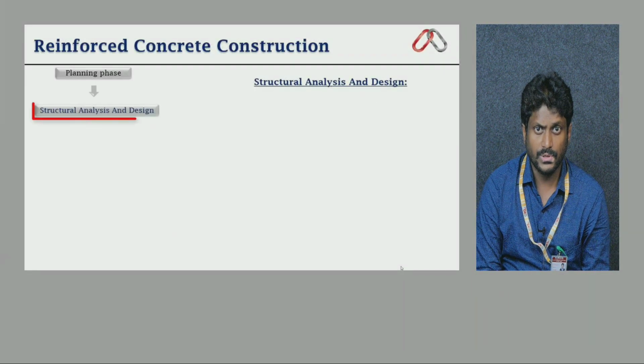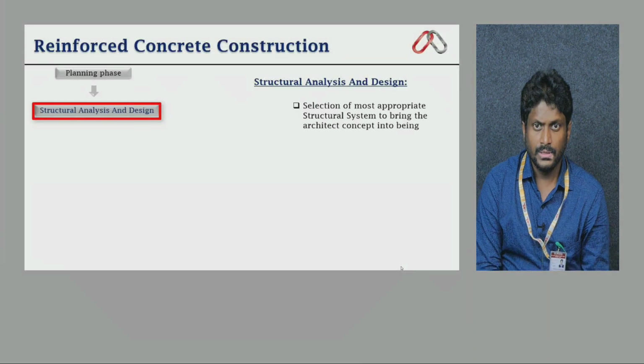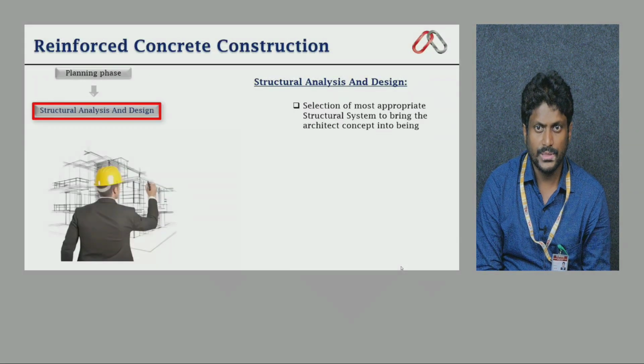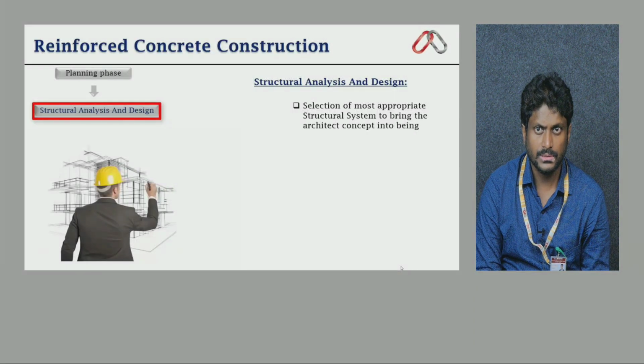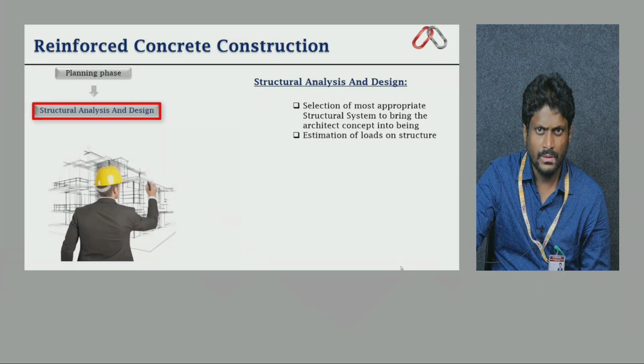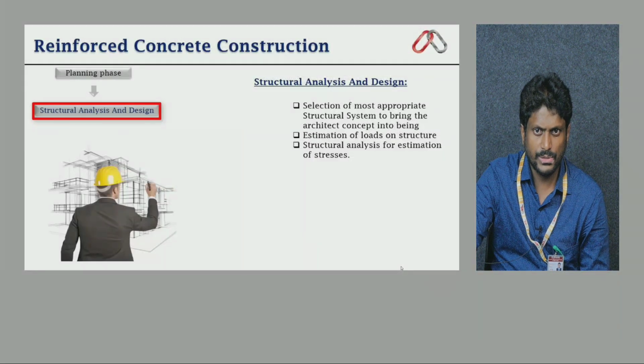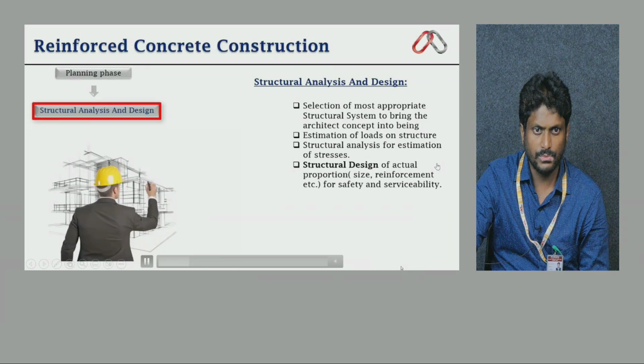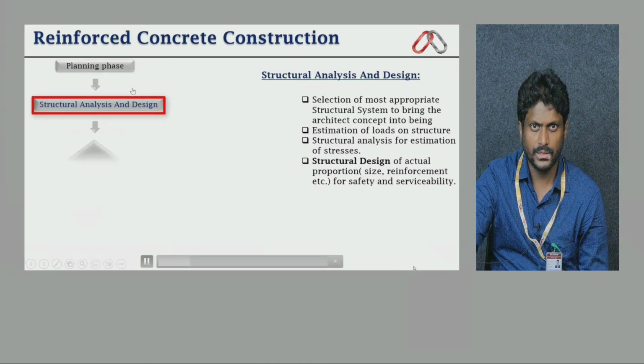After the planning phase, we have the structural analysis and design phase. Selection of the most appropriate structural system to bring the architectural concept into being, that is another important task. Then estimation of loads on the structure. Then structural analysis for estimation of stresses. Then structural design of actual proportion, size, reinforcement, etc., for safety and serviceability point of view. So this is a very important phase in reinforced concrete construction.